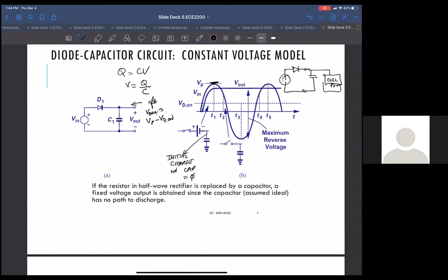But if I have a cell phone connected here, okay, sorry, I'm redrawing the same darn thing over and over again, I can model that cell phone as drawing current from this capacitor. As it's charging, it's pulling current from the capacitor, pulling charge from the capacitor. So I can model that cell phone as a resistor. Charge is going from the capacitor to my cell phone.